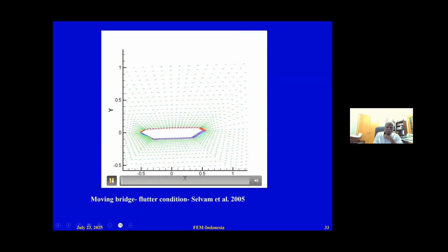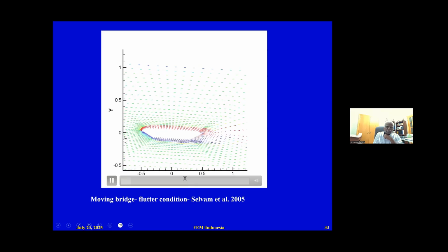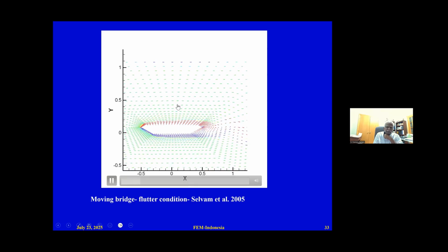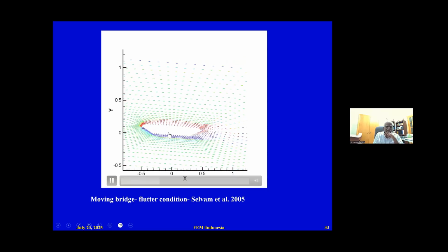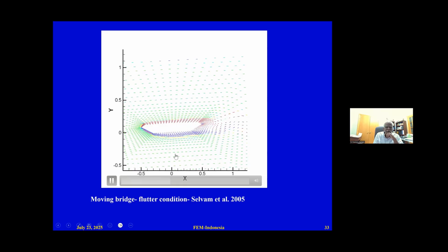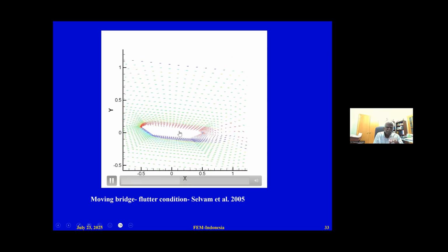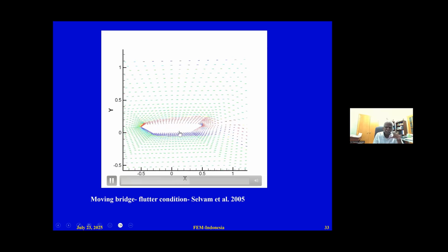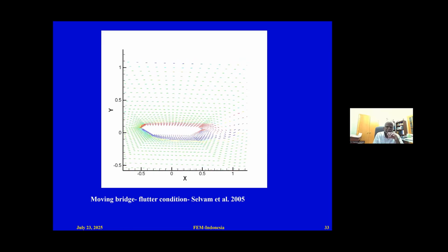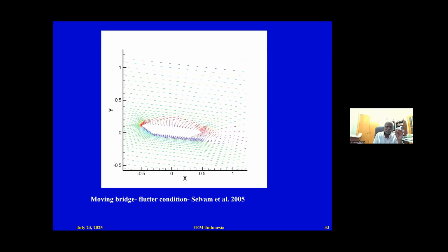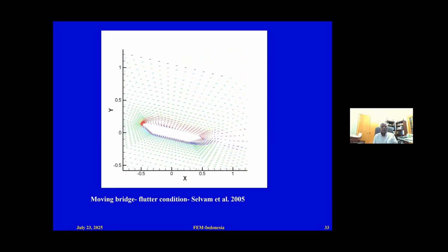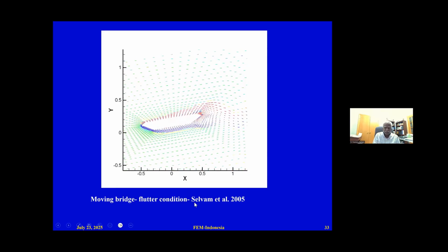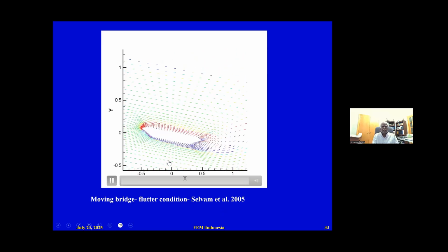You can see the animation of it, how the vortices grow when the bridge and the air around interact, and this is a stage we call the flutter stage. So we are able to predict the critical velocity beyond which wind flutter happens. Anyway, I thought I'll put it in. You can see that this is work done sometime around 2005 or before.